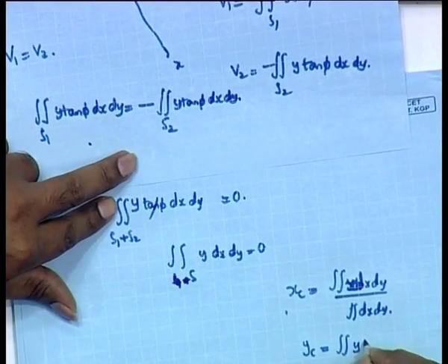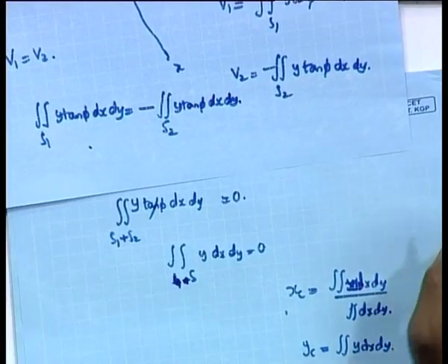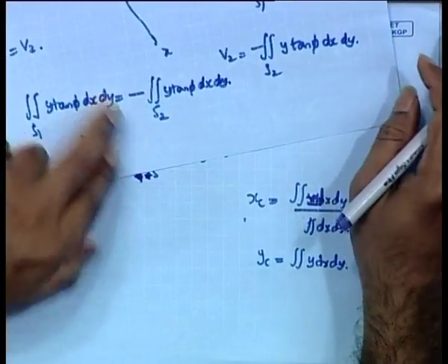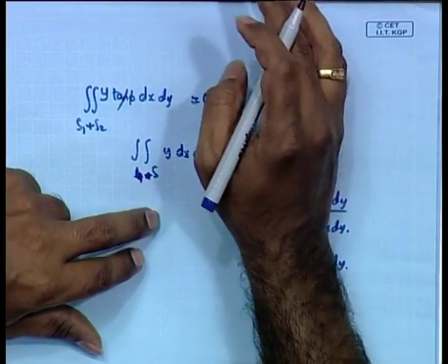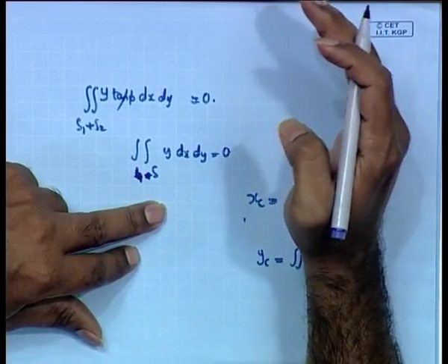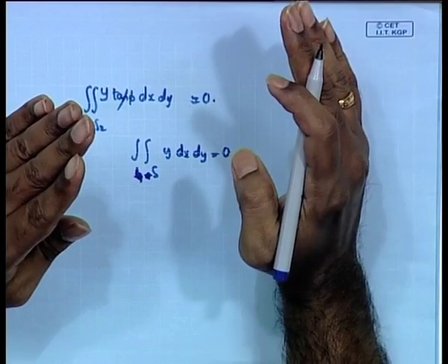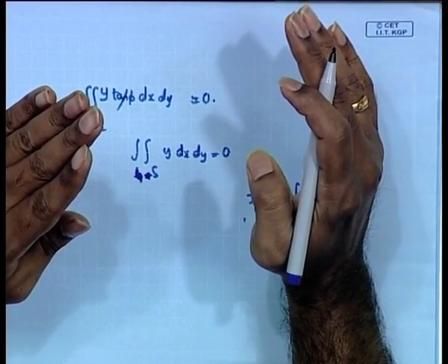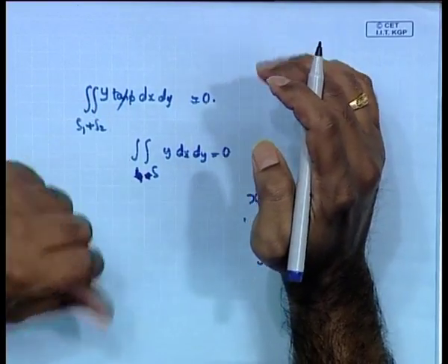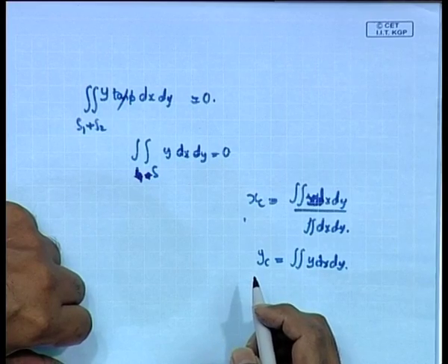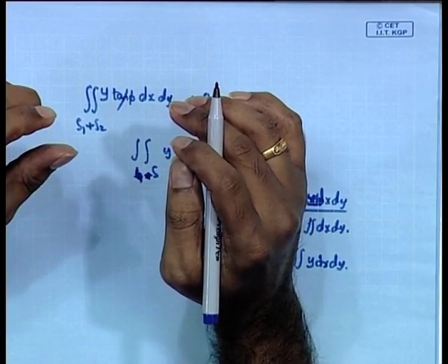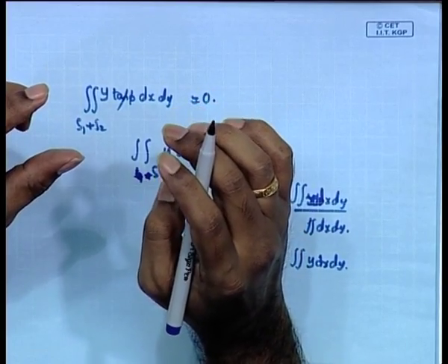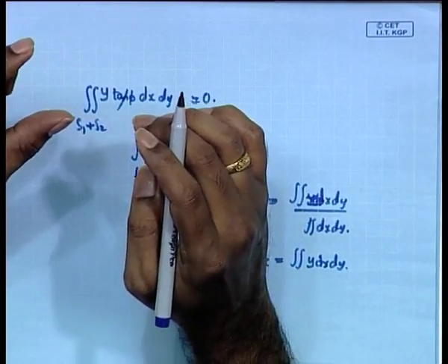So, from this what we get is that if you assume the initial water line to be W0 L0, now after an inclination, the intersection along the axis of inclination, if this inclination is very small, will be a straight line that passes through the centroid of the body.